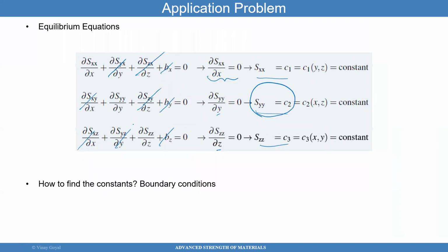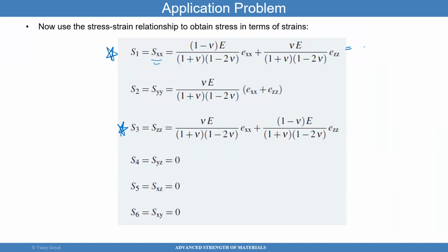and it's constant. So I can make this equal to minus P naught. I can solve for epsilon ZZ out of this equation, or I did it out of this equation because this is equal to 0, the whole thing. So I can solve for epsilon ZZ, plug in what epsilon ZZ is in here, and then solve for epsilon XX. So that's what I'm trying to do, solve these two equations in stars simultaneously.